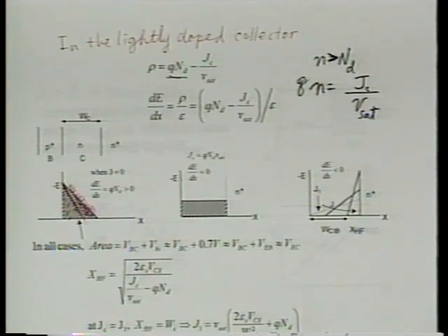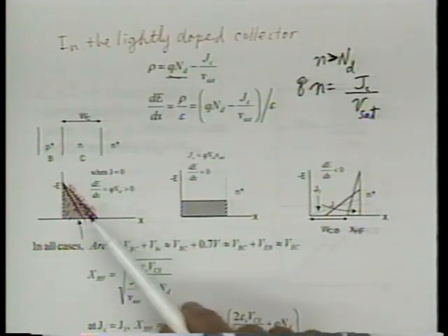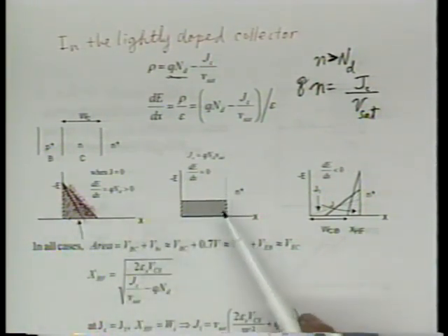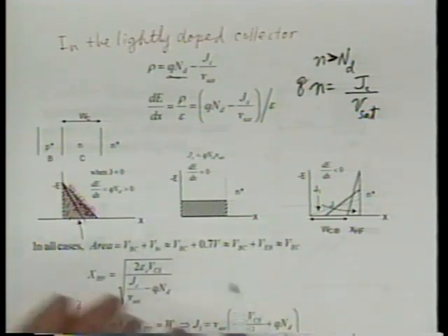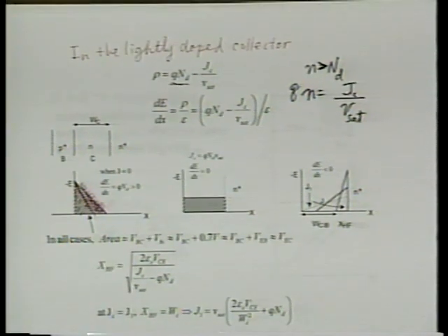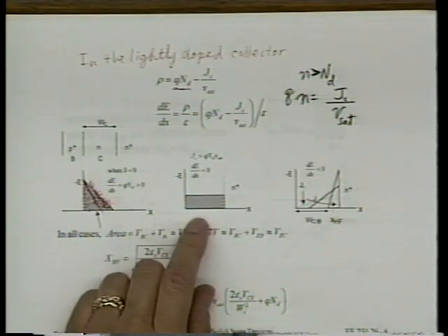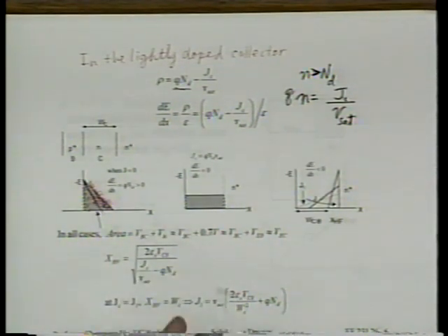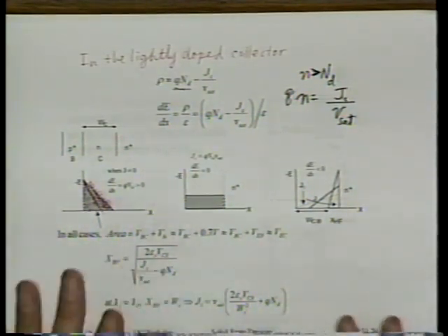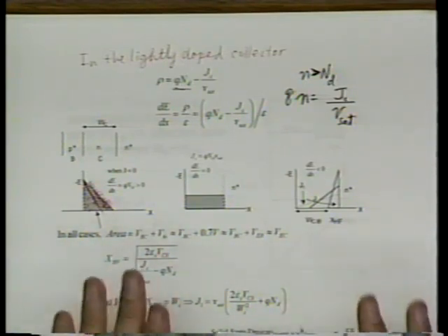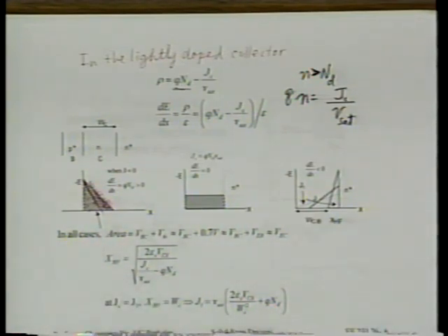The area between these two curves will be equal. Why? Because they are equal to the applied VBC. Area under this electric field is equal to the voltage. Since we fixed the bias VBC, the area should be equal. But the shape will be different. This still does not hurt us. At this point, the transistor is still pretty fast. Next will be the problem.